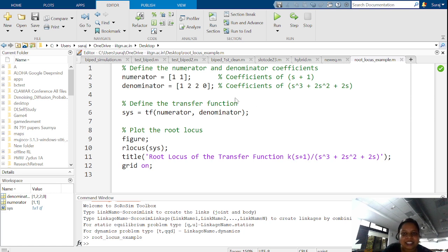But in our case, what has happened? This region in which this line has been made from a pole to this zero is lying on the root locus. This was a simple unity negative feedback system, and the other thing was that k was greater than 0. In our case, k is less than 0. Now, if k is less than 0, my conditions are changed and I do not have this midline. I have this area lying on the root locus after this pole, and this area lying on the root locus before this zero.